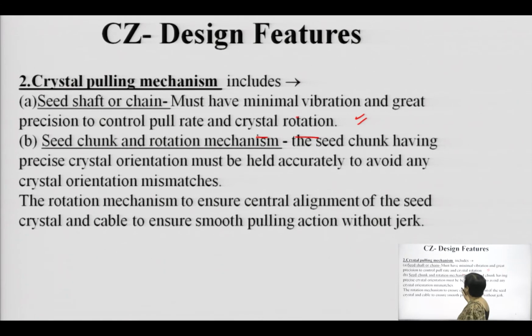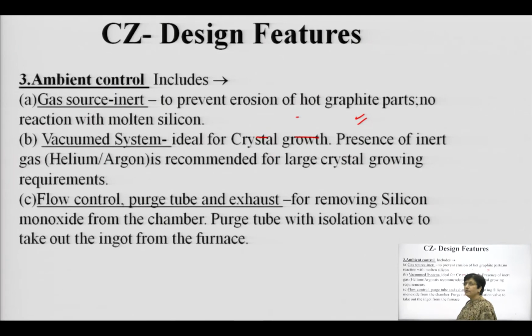The seed chuck which is being held up by the chain pulley mechanism has to be very stable, very precise, and the rotation mechanism also should exactly ensure that the central alignment of the seed crystal exists throughout the process. Third and the most important thing is the ambient.